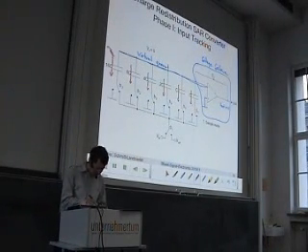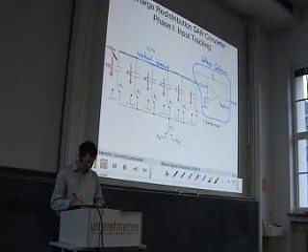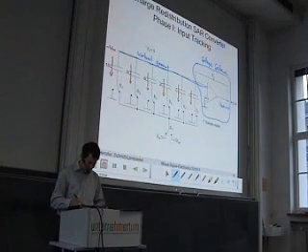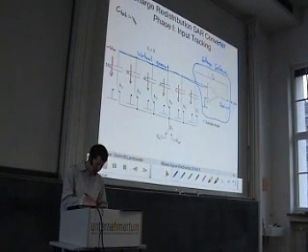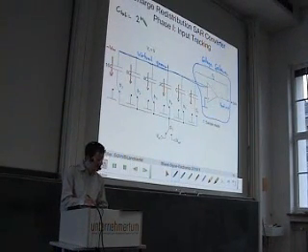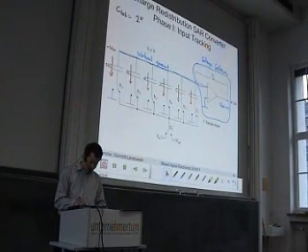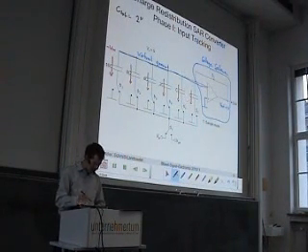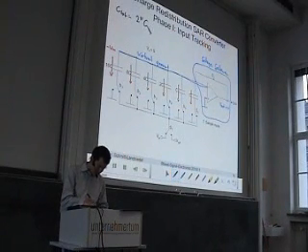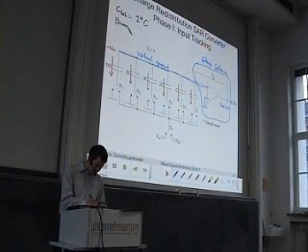And it is equal to minus V in. Okay? The total amount of capacitance here is C total equal to 2 to the power of n, normally minus 1 if we have such a binary weighted network, but you can see here we have the LSB kept twice, so we have 2 to the power of n times C as a total cap, and we have this in a binary weighted form.